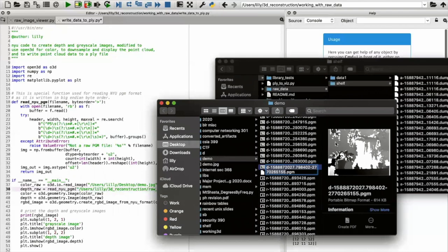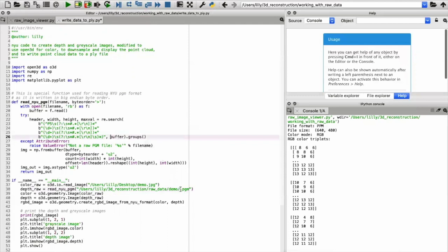You can see how the depth works there. The depth is very much affected by light. I tend to work on stuff mostly at night, and I've taken most of my sensor data captures at night, and the depth data was almost completely flat. I thought there was something wrong with my code, but when I do it during the day, it actually works so much better. So yeah, very much affected by light, and the depth data might look kind of wonky because the sensor's pointed at a window.